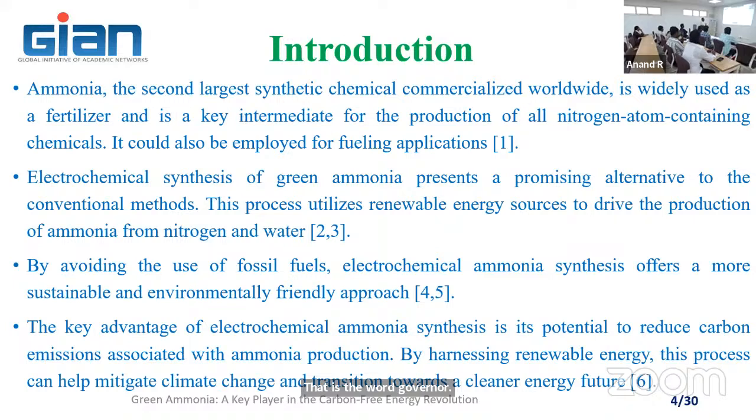Yesterday, we saw some of the green methodologies, where I spoke, and the other speaker also mentioned in his lecture, the green method of producing ammonia by keeping the Haber-Bosch reactor, with the only modification being avoiding the steam methane reforming. We are electrolyzing the water into hydrogen, and nitrogen comes through membrane processing or absorption methods, where nitrogen and some oxygen are separated out. Nitrogen can be used in the Haber-Bosch reactor. In that method, we are eliminating the carbon dioxide completely. The ammonia we get by using electrolysis along with the Haber-Bosch reactor is free from carbon. That is why it is called green ammonia.